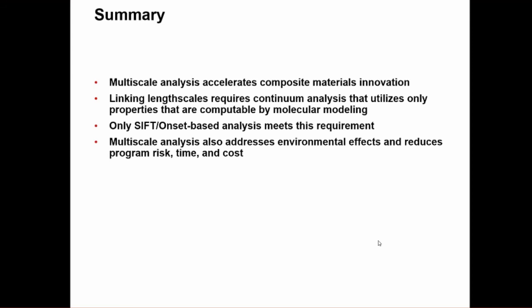Multi-scale analysis also addresses, like we stated, the environmental effects and reduces program risk, time, and cost, because those things are all often tested at the very end of the program because of the requirement for conditioning coupons, which takes so long to do. It can take weeks or even months to condition a coupon for moisture and temperature. So multi-scale analysis is a very, very powerful tool for both material suppliers and aerospace OEMs in moving forward with materials innovation.